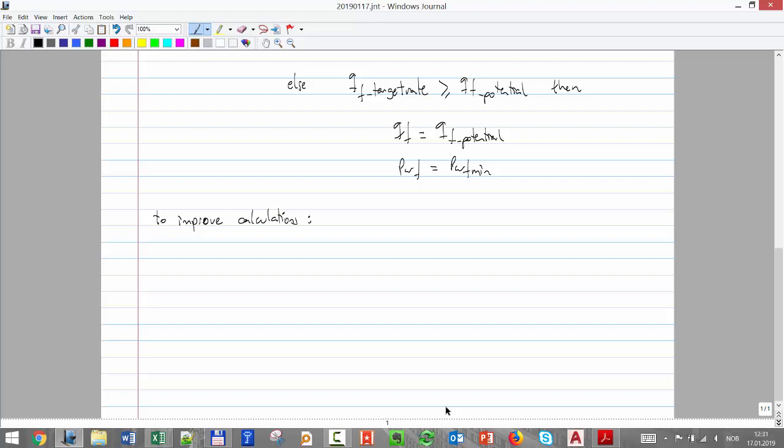So to improve calculations, Z actually is a function, as I mentioned before, of pressure and temperature. Well, actually, let's go a bit back. If you remember, Z is this factor that I have in the real equation of state relating pressure, this is 1 over density, I have this R, ZRT. Temperature, a gas constant, pressure, density, and this Z is a relationship with that. And I can use that expression with high confidence for gas.